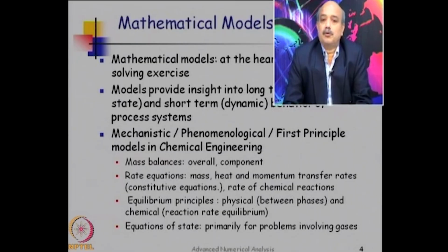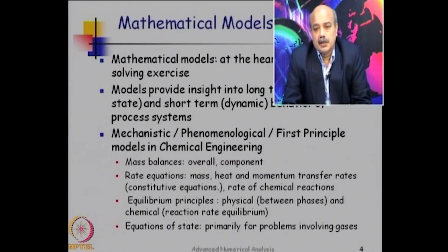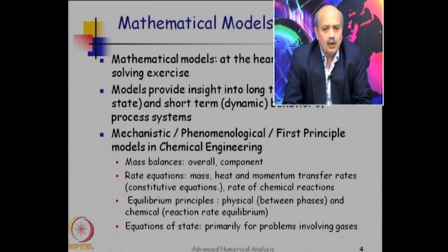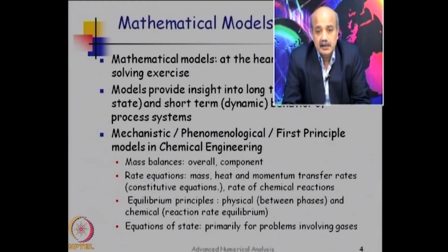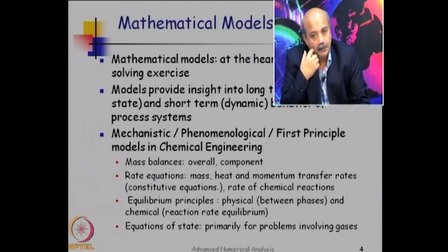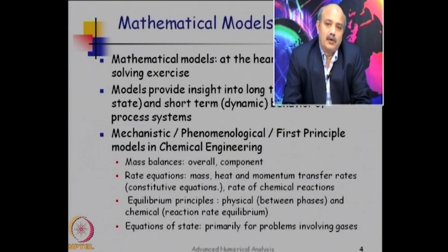models composed out of rate equations, mass, heat, momentum transfer. There are constitutive equations, then chemical reaction rate equations. There could be equilibrium principles used while doing modeling between different phases. Also you may have to use equations of state for systems involving gases or multiple phases.